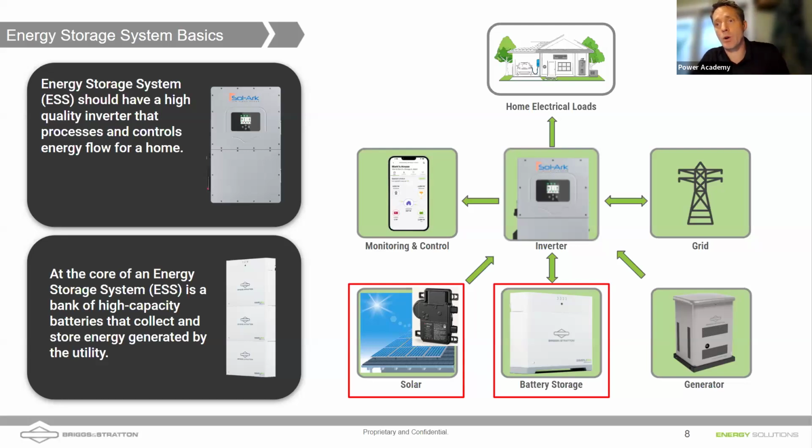Yeah, you mentioned two topics there. One, the energy loss when you do invert, right? When you convert the electricity from the DC that the solar panel produces to AC, you lose some energy, and that is the production of heat inside the inverter. And then converting back to DC to charge the battery again, there's another conversion process, AC back to DC. So there are losses in both of those steps. Typically DC coupled systems are somewhere around 10% more efficient. You're looking at around 95% efficiency on battery charging from solar when you're doing it with a DC coupled system. Now, there are plenty of variations in that, so I have to say 95% plus or minus, right?